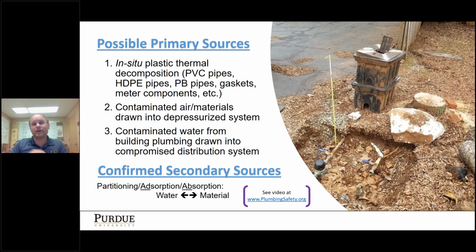And then we can also have the hydrants and other types of structures. Sometimes firefighters, as they run away from the fire, can't shut the hydrants, and so sometimes when there's depressurization or low pressure, the contamination can get in through those hydrants as well.